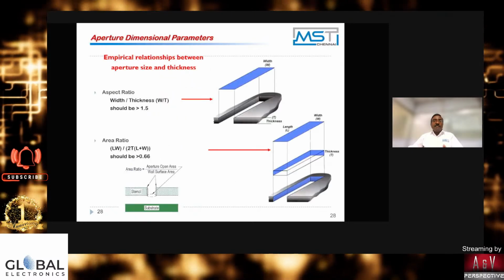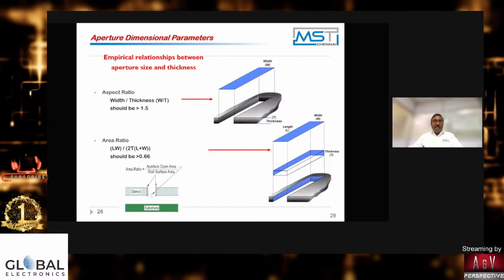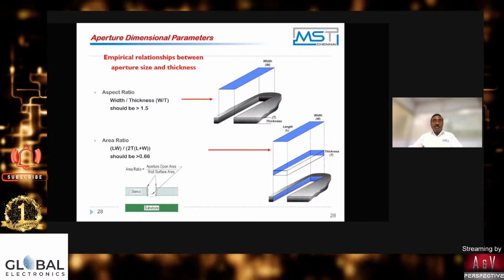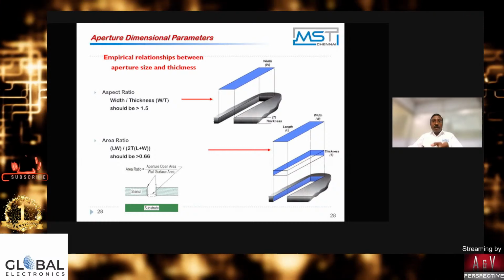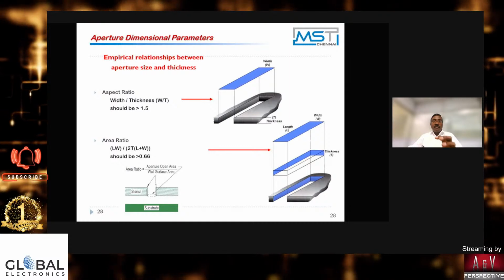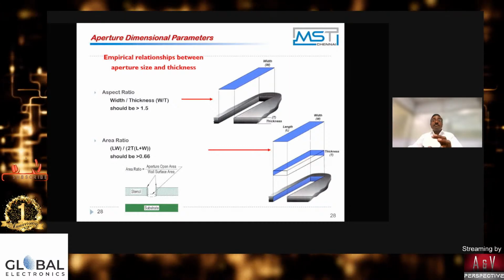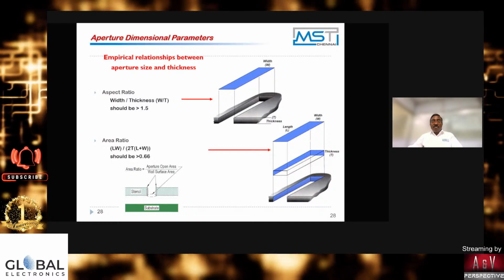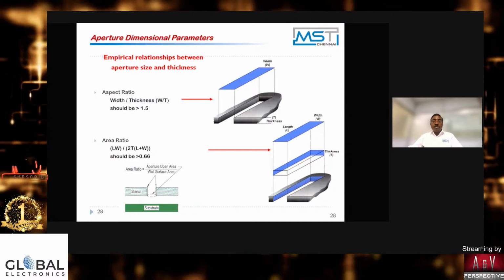It doesn't require any tension and other things. But for high-density boards, mainly mobile phones and laptop and desktop boards, and some recent automotive parts, which is the ECU and audio equipment, mainly the engine control units, definitely need a fine grain stainless steel. That will give you better hole wall definition and edge definition.